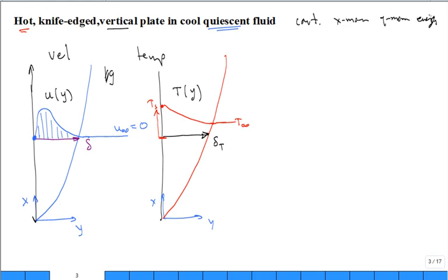Let's not take a look at that. Let's focus in on the x momentum equation. We have rho times u, partial of u with respect to x, plus v, partial of u with respect to y. What does all that represent? Keywords. I'm looking just for keywords. What does that represent? Advection of momentum. Flow, sweeping. So it's advection of momentum.